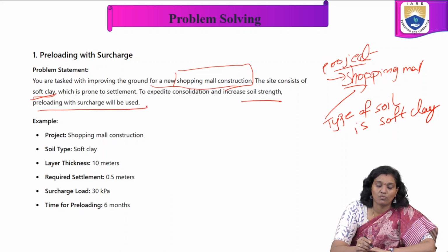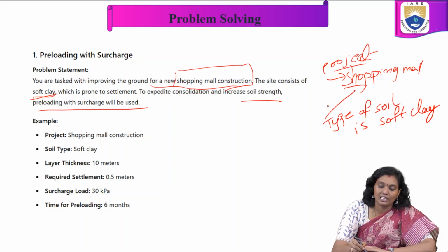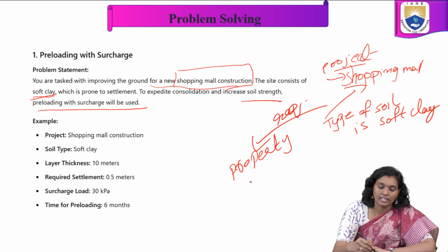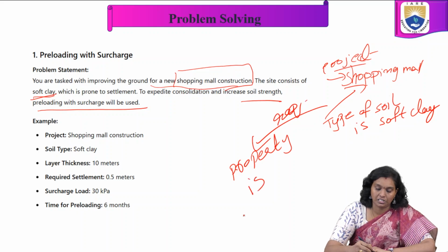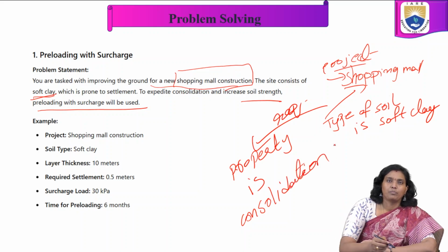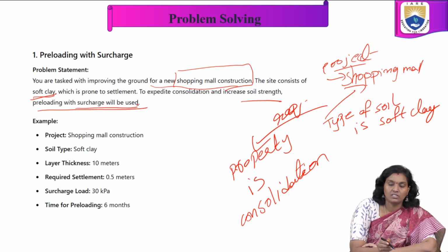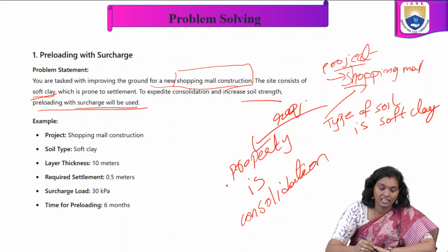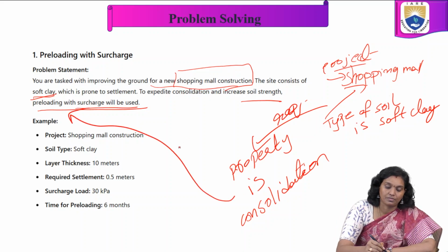In this case, the desired property we require is consolidation. For this consolidation, as a mechanical technique, we choose preloading with surcharge. This is the technique we used.